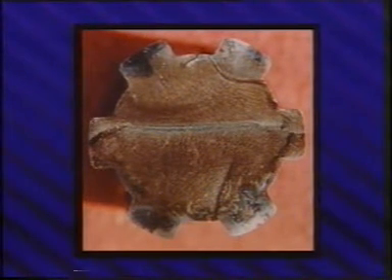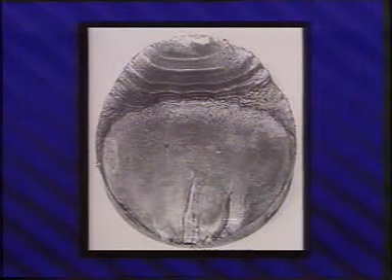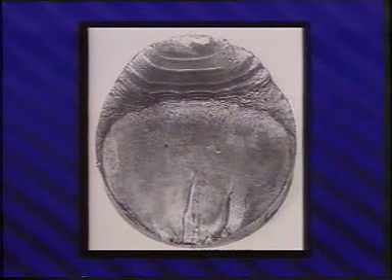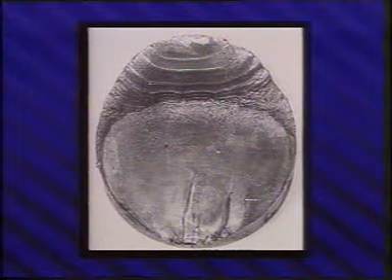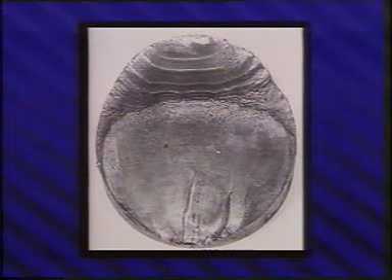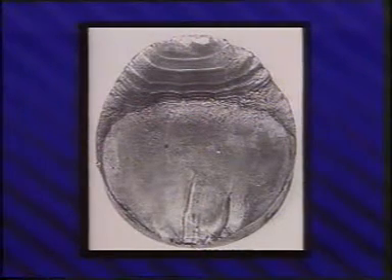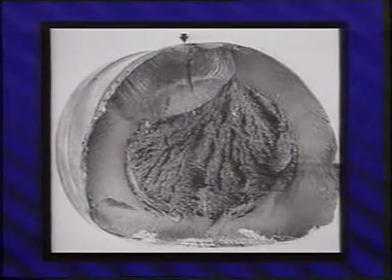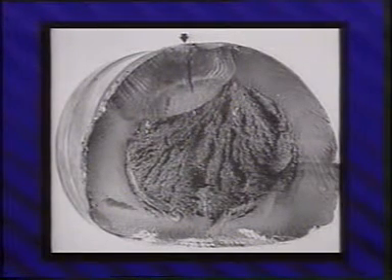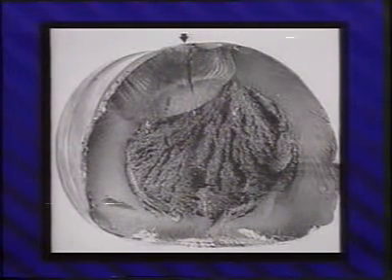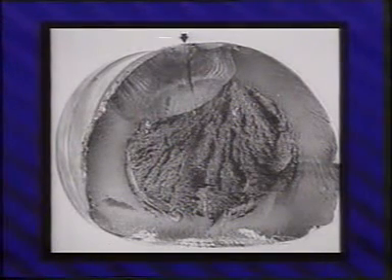of failure. On the macroscopic scale, early crack extension occurs under conditions that give a typical smooth-textured, grained, flat-faced surface to the fracture. When produced under random repetitive loading or sequences of high and low stress amplitudes, the characteristic beach marks frequently result. It is possible for a fatigue crack to originate in the hard, strong region of a part and propagate into softer, weaker regions. This is usually due to heat treatment, imparting intentional variations to the properties of the material.